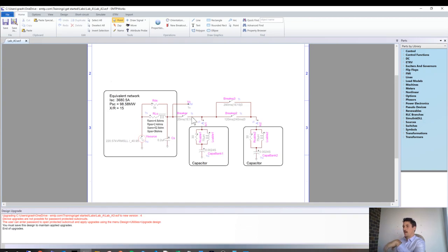Now, when we go to lower frequencies, this becomes a short circuit, and we have those two capacitances connected in parallel, so we can put them in one. And then we have another RLC circuit, which is the two capacitances in parallel with this inductance. So basically what we can guess here is that when we energize this breaker, we are going to get two natural frequencies. One is this inductance with the two capacitances in parallel. One is this inductance with the two capacitances in series. So we will see that with the simulation.